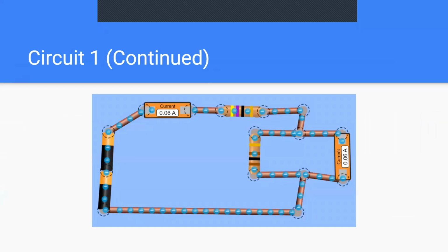When the ammeter is parallel to the 100 ohm resistor, Kirchhoff's node rule states that the current going into the parallel portion will be split between the resistor and the ammeter. Since the ammeter has a resistance of 0, the total resistance of the parallel portion decreases. According to Ohm's law, if the voltage stays the same and resistance decreases, then current must increase, which is seen in the ammeter's recording.